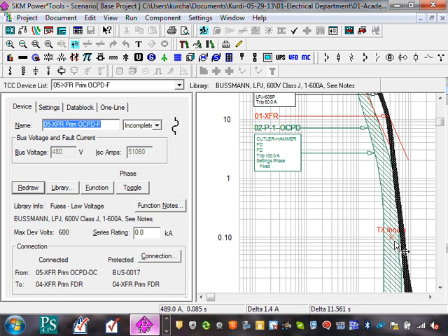This one here is the inrush of the transformer. So my fuse is allowing my transformer to start. If I move this one here, every time you start, because of inrush of a transformer, your circuit breaker is going to trip. What I like to mention is that if you can coordinate, you can always get smaller fuses or circuit breakers than what the code allows. And a quick reminder, why do we care about smaller circuit breakers and fuses? Because they will get you better arc flash and protection, a smaller arc flash category and better protection as you work on this equipment.